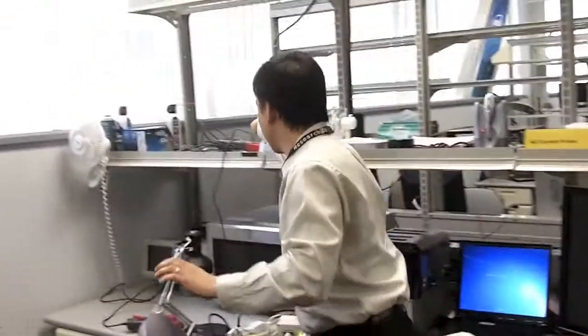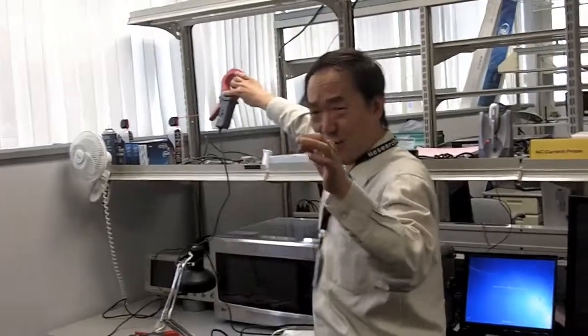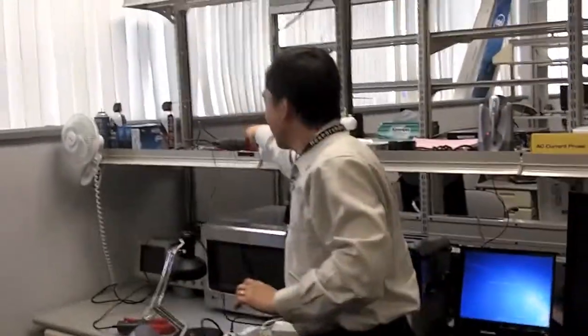Now today, if you want to measure energy, you would need to buy some sort of device, and in my panel I actually have a circuit breaker, but you would have to take out the metal casing, expose your 200 amp service, and then put in 2 current transformers. This is kind of a larger current transformer, but you would have to put it around these thick wires, about this thick, and then hook it up, and trust me, that's not something you really want to do, because that's 200 amps of service. It could be very dangerous. So you would probably have to hire an electrician.